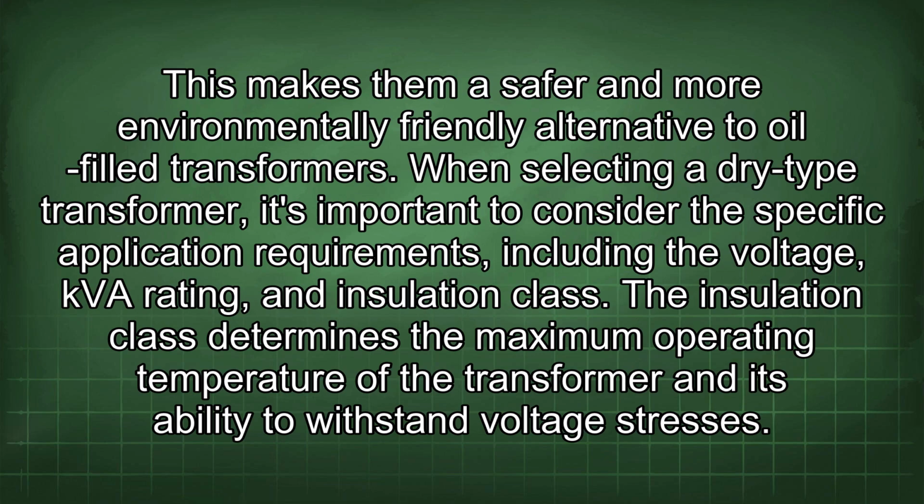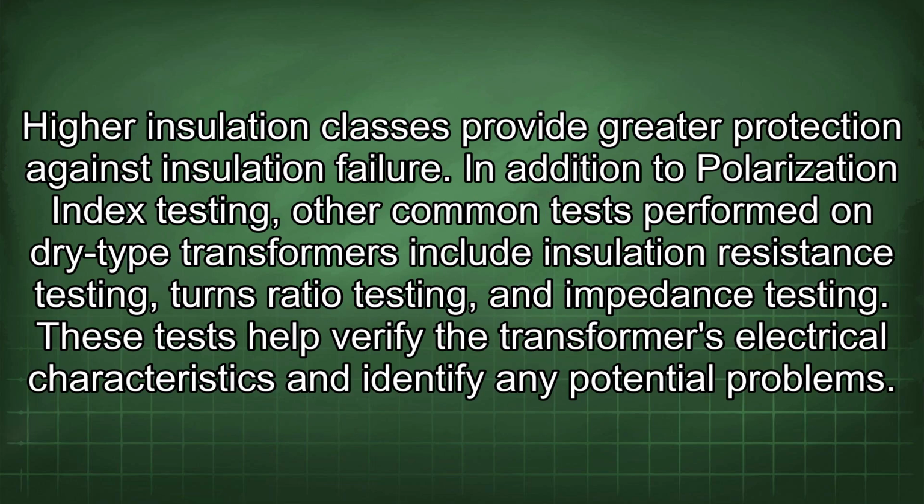When selecting a dry-type transformer, it's important to consider the specific application requirements, including the voltage, kVA rating, and insulation class. The insulation class determines the maximum operating temperature of the transformer and its ability to withstand voltage stresses. Higher insulation classes provide greater protection against insulation failure. In addition to polarization index testing, other common tests performed on dry-type transformers include insulation resistance testing, turns ratio testing, and impedance testing. These tests help verify the transformer's electrical characteristics and identify any potential problems.